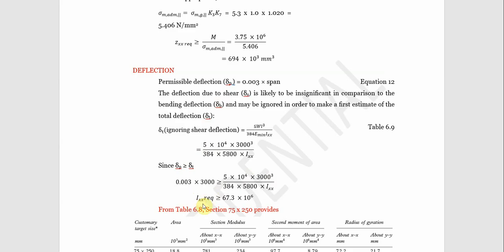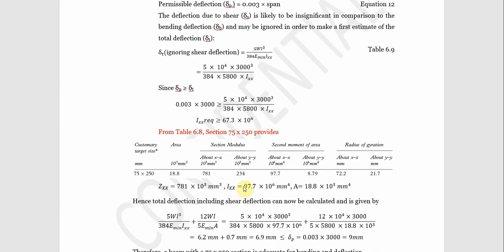So we'll be able to get our second modulus of area, which is the section modulus, which is greater than or equal to 673 times 10 raised to the power 6. Now this section modulus is what we will use in selecting our member size. Having gotten this, just like the way we did for steel, this is what we are going to check.